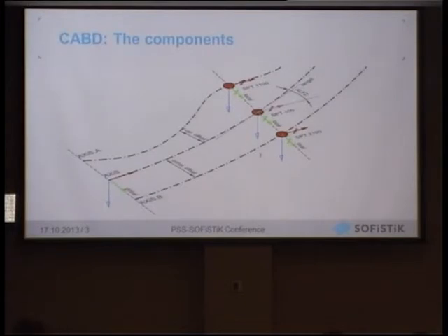And if you think about a bridge being maybe in not a simple arc radius alignment, but maybe intermediate element, like I would call a spiral element or clothoid element, where you have maybe a constant change of curvature, then it's very difficult to construct and to generate the geometry of a constant offset. You will understand this, because having a radius, an offset of 3 meters, is just increasing the radius by 3 meters. But having a spiral element, it's not that easy to maybe generate